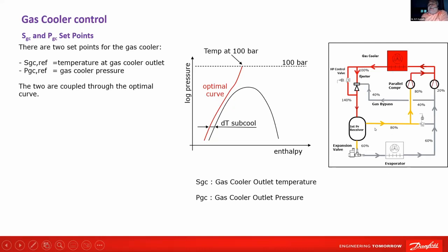Gas cooler evaporating pressure is managed by itself. It has a controller, which I was explaining. So when cooling is required, it ensures independently what the cooling required is. Accordingly, it gives liquid and vapor is formed. Now, on the other side, we are trying to regulate the gas cooler pressure. How? Based on the cooling media temperature. Like if air temperature is 30 degrees centigrade, we try to maintain it, and if you have an economically sized gas cooler, you may have 35 degrees centigrade as the gas cooler temperature. Now, according to that, it will find what pressure is required, maybe 90 bar or something like that, and it will try to maintain that. Accordingly, it varies the loading on the ejectors.